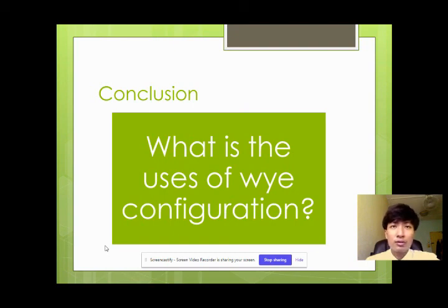Hence the insulation required in Y connection is nearly 57.7%, which can be used for high voltage connection, than the insulation that we require in the delta connection for the same line voltage, and hence the cost for insulation will automatically be reduced.